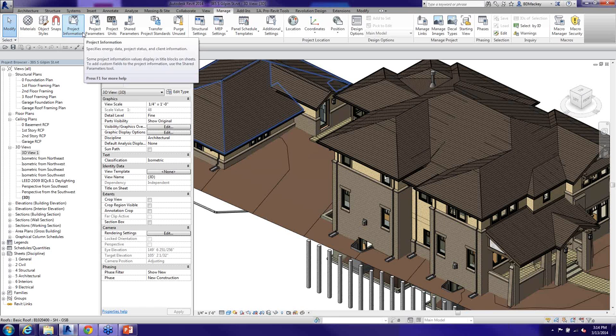It's also funny that I have noticed that if you put yourself really far north, like Anchorage, Alaska, and you do it during the winter or summer solstice, it completely freaks Revit out. It doesn't understand how to deal with 23 hours of sun or 23 hours of dark. So just thought I'd let you guys know that if we have anybody listening from way up north, I have seen Revit have issues with rendering internally. I don't know if I've tried that on the cloud rendering.